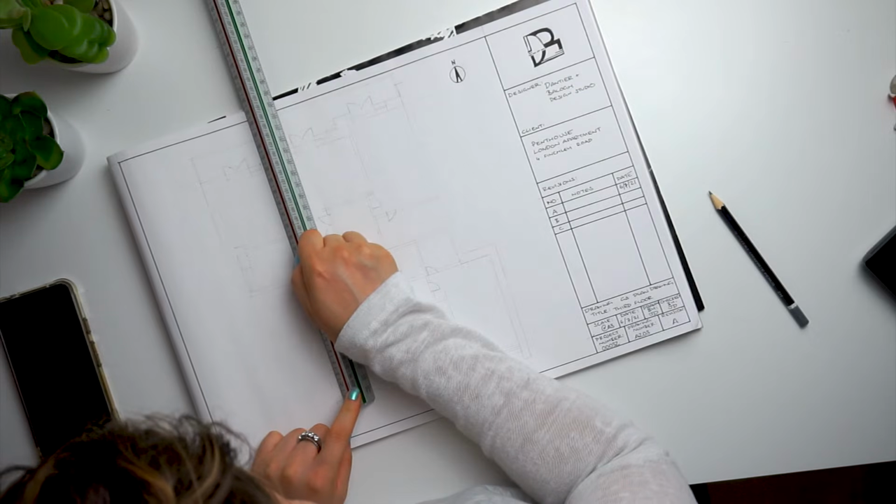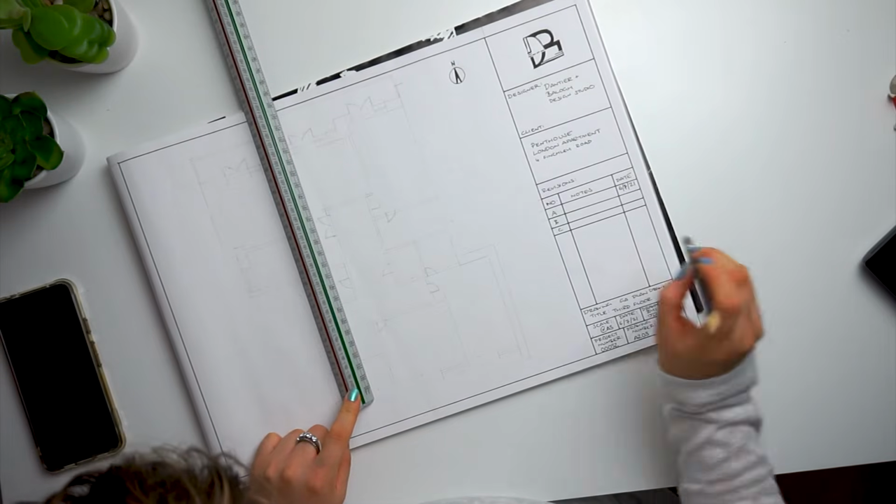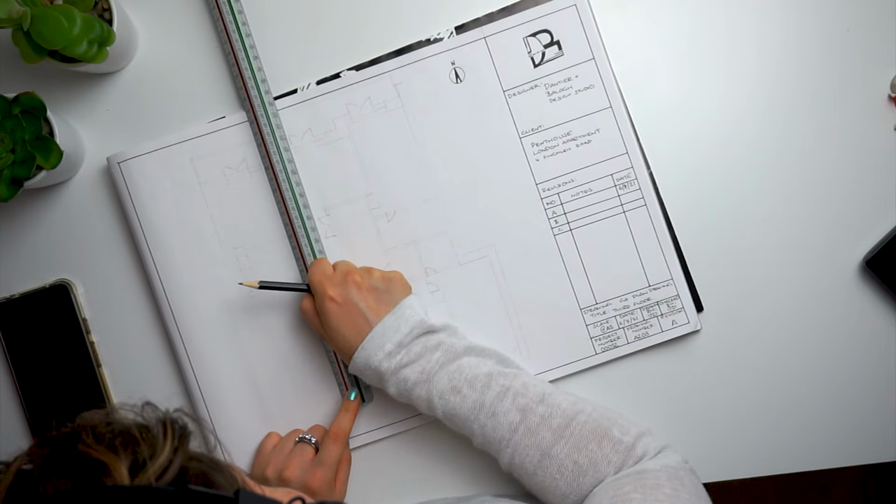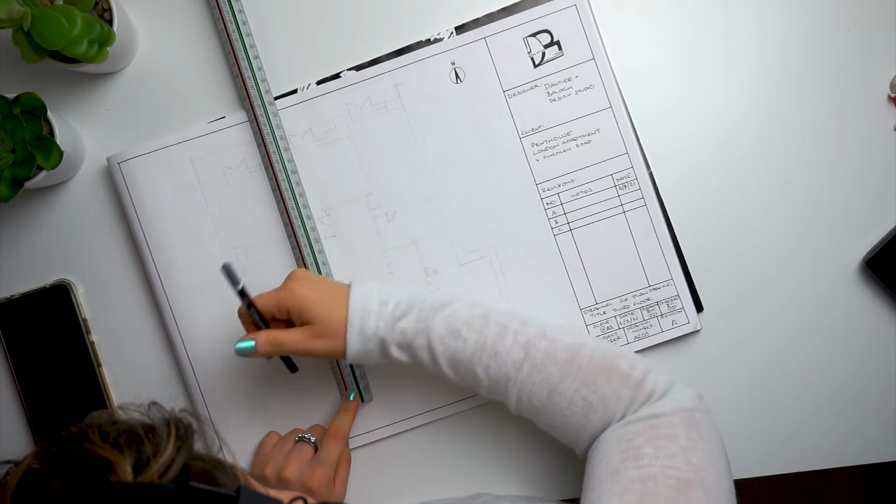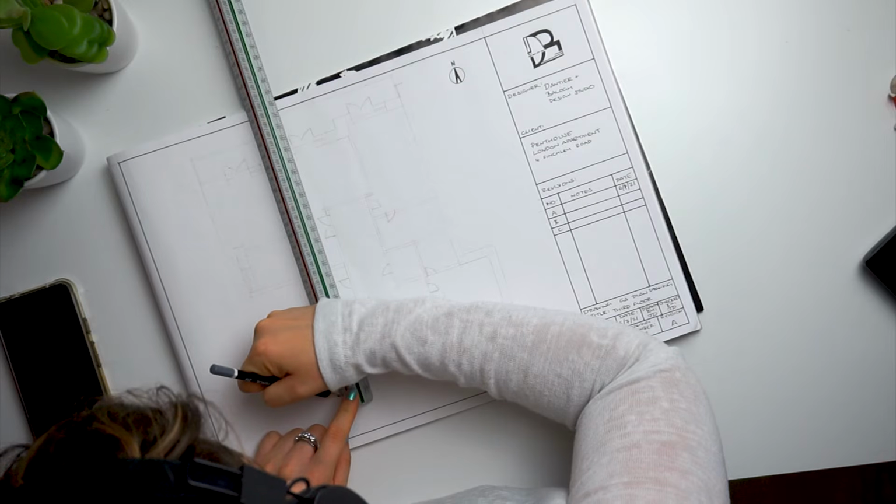I like an A3 size because it fits the drawing on most times, and if it doesn't, then I up my scale to 1 to 200. And also it's not too oversized where it makes it awkward to transport. It's also a big must to make sure that the floor plan has a north point / compass on the drawing so that we know the orientation and where the sun will enter throughout the duration of the day.